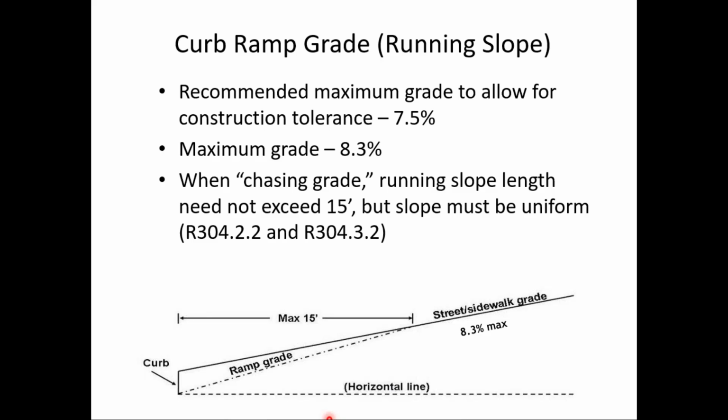And when you're chasing grade, the running slope length need not exceed 15 feet, but the slope must be uniform.